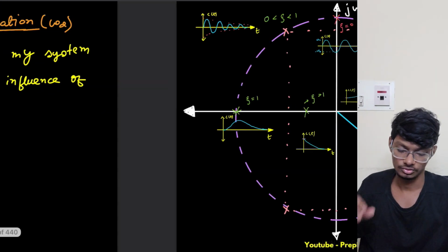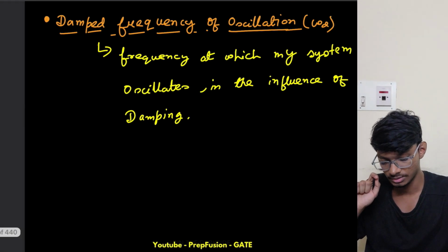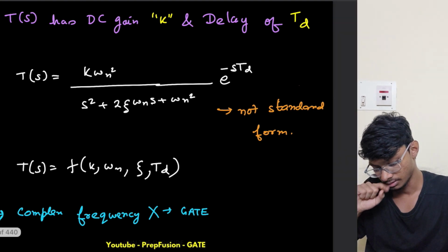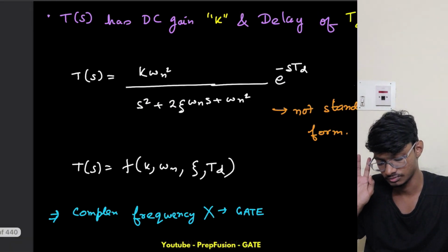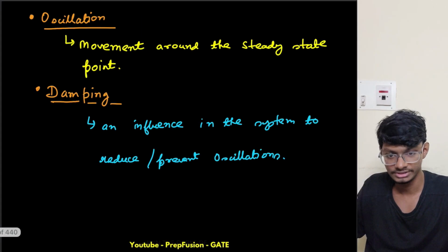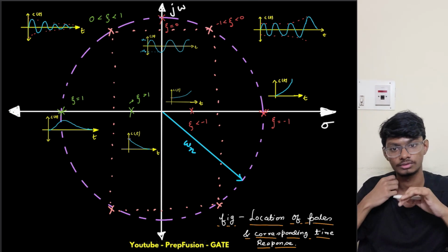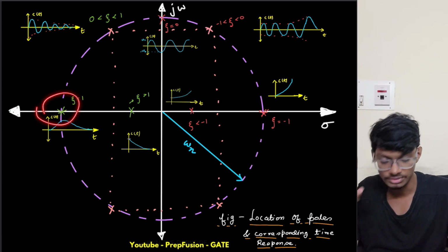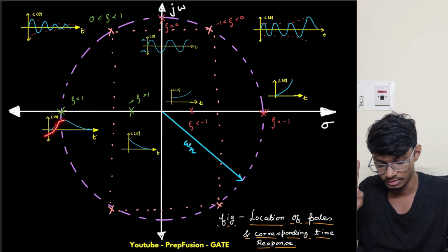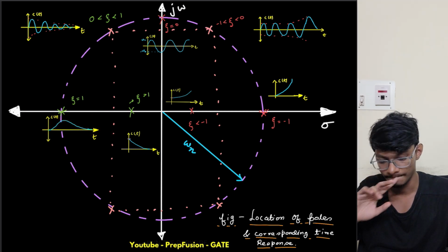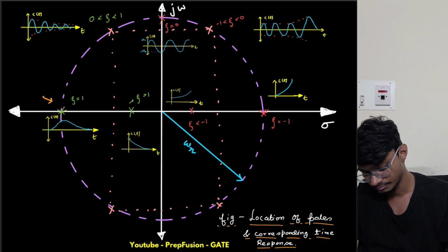Okay, and I directly come to the impulse response, right? This was the second order system standard, and the impulse response, not this one, right? For all of them, I have drawn a circle and told you how to remember this. So what was the system here? This system was critically damped, as you can see, it reaches and then goes down. So no oscillation is present. So this is basically critically damped.